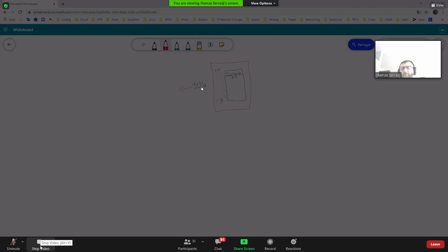Not by bits anymore. Yeah, because I have 1024 possibilities. This is a kilo, guys. This is kilo, just 1000. Why go into gigabyte and whatever byte? I have 1000 addresses, so it's 1 kilo of address. Now in each address, I can have 1 byte. So it's going to give me 1 kilobyte. So this chip capacity is 1 kilobyte.